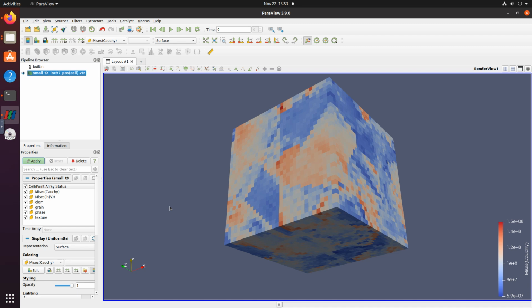But basically this is a very basic simple example, starting from the default given libraries or files, to run a simulation, to extract its results from a binary file, to average them, or look at the overall average stress strain behavior of the material, or for example on a specific increment, look at the local distribution of stresses or strains. We can also look at the local distribution of several other things. I have not exported them in this file right now, but we can do that as well.